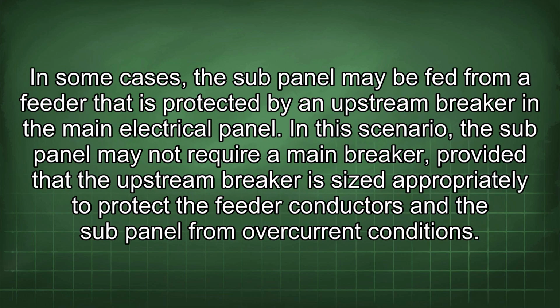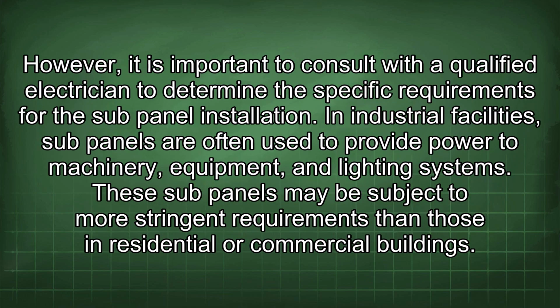In some cases, the sub-panel may be fed from a feeder that is protected by an upstream breaker in the main electrical panel. In this scenario, the sub-panel may not require a main breaker, provided that the upstream breaker is sized appropriately to protect the feeder conductors and the sub-panel from overcurrent conditions. However, it is important to consult with a qualified electrician to determine the specific requirements for the sub-panel installation.